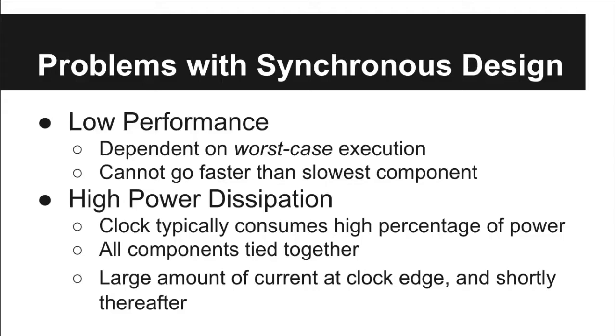The other major setback is the issue of power and heat. Since power equals heat, there is a limit to how fast we can make the clock speed go before heat becomes an issue. Running a continuous clock and a widely distributed clock signal takes a lot of power, as the clock is continuously ticking for the entire time the system is on, regardless of whether a particular circuit is actually receiving inputs or not. It's still drawing power because the clock is connected to it. And since components of a synchronous circuit are tied together to the clock, this means that to some degree all components are active. Components, active or inactive, are continuously drawing power.